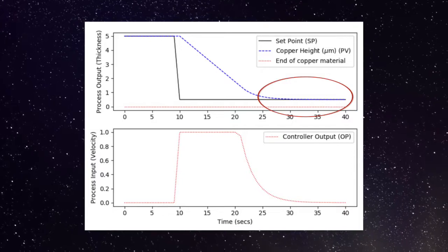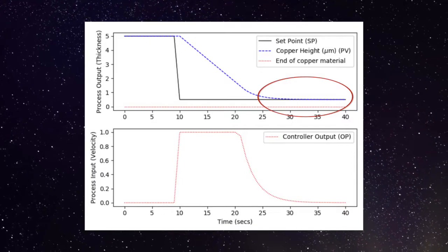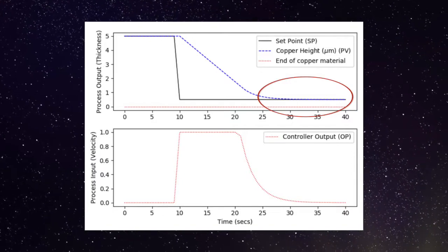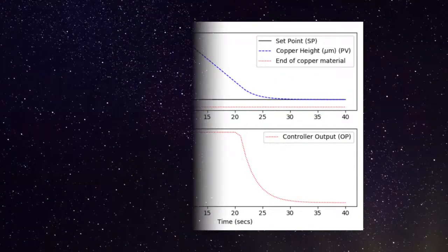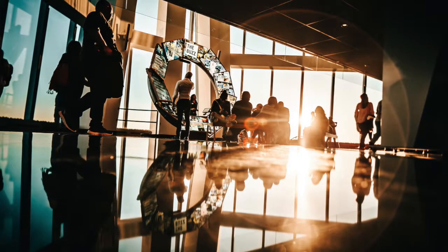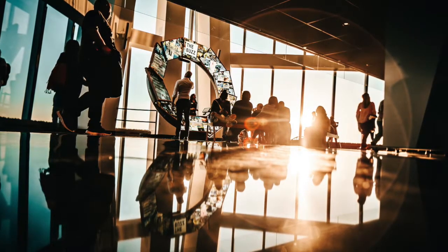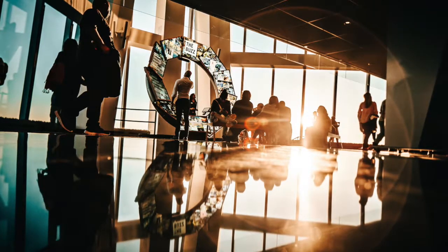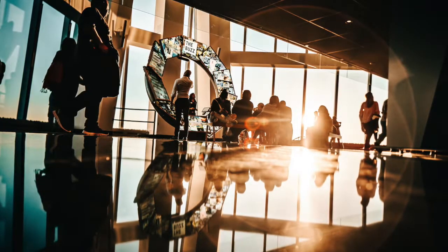Because our system responds in a similar time frame as other CMP systems, this lends credence to our simplified model behaving as expected compared to a more robust model. Current methods measure the thickness before and after the process because currently it is the more accurate method to measure copper layer thickness.